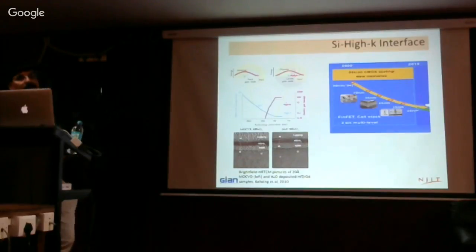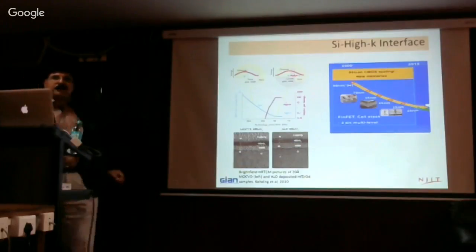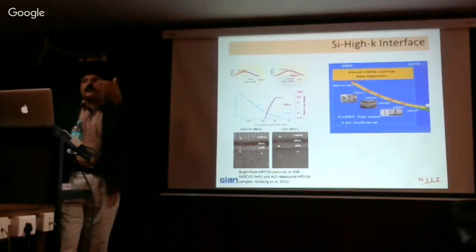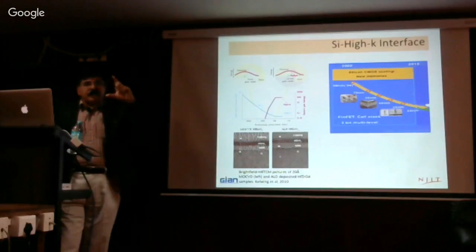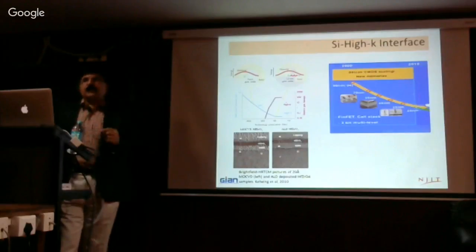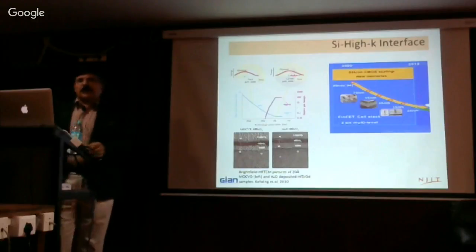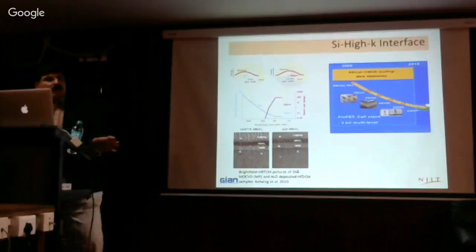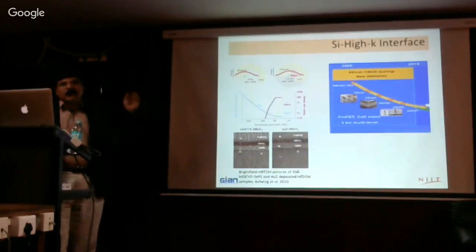But because you have silicon oxynitride, the minimum thickness goes to around 1.2 to 1.5 nanometers. So that is not acceptable. Then you have a very thick layer, and you cannot scale the EOT below 1 nanometer. It would be something like 0.9 or 1 nanometer. Now, these most recent devices need around 0.5 to 0.7 nanometer EOT. So that's why this was not done, with mostly silicon dioxide being used instead.